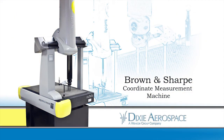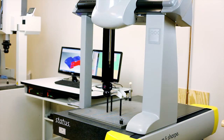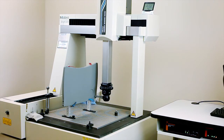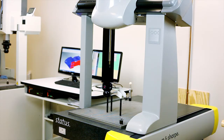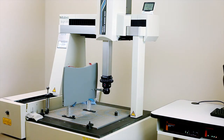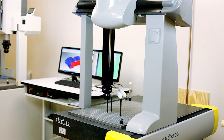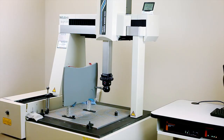The Brown & Sharp and Mitutoyo coordinate measurement machines are used for all reverse engineering that require three-dimensional measurements. The CMMs are pneumatic and electric-driven machines with interchangeable ruby-tipped styli. After parts are mounted, the CMM is programmed by the operator to carefully trace all desired profile features. The CNC-driven machine utilizes PCDMIS and SolidWorks to interpret the part shape and feature locations. These two machines accurately trace profile forms, find hole locations, and carefully collect all geometric dimension and tolerancing requirements specified by the project engineers.